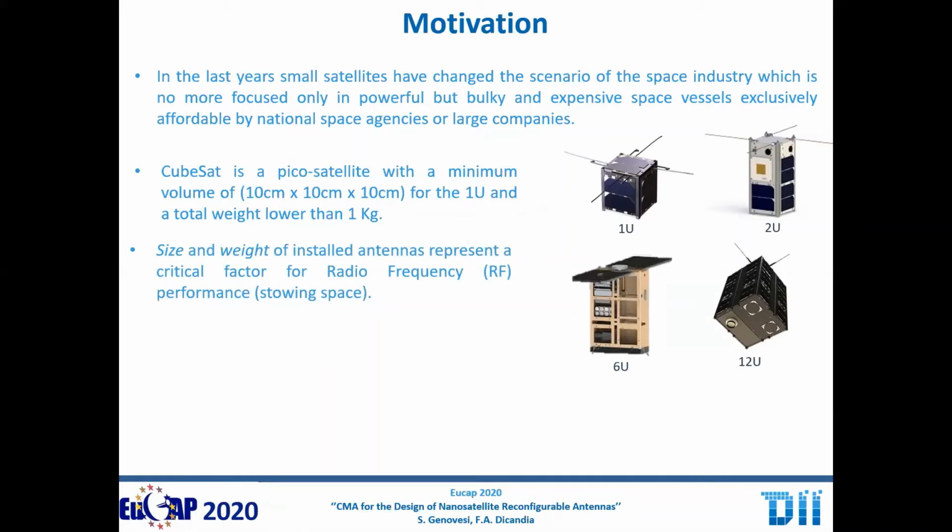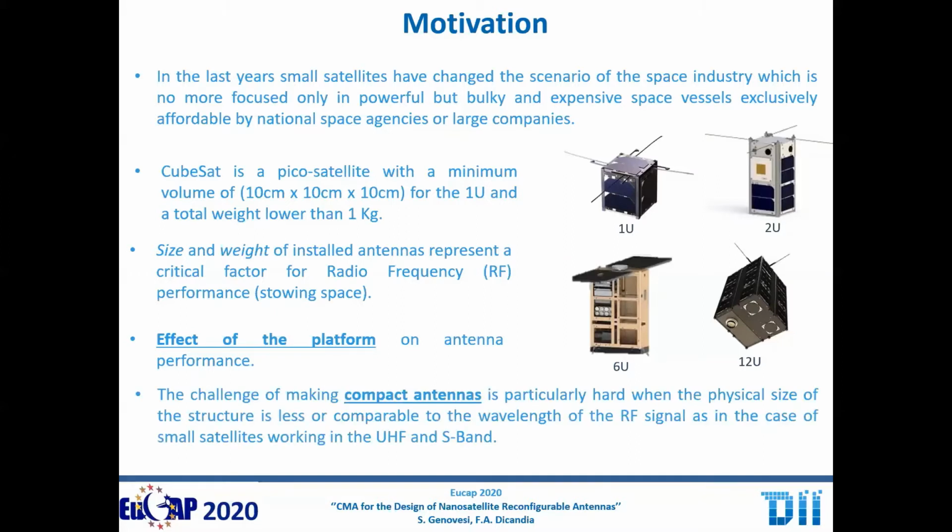Of course, since the platform is very small, size and weight of the antennas are a critical factor, and especially also the stowing space if we need to deploy antennas. And also the effect of the platform is really important, especially for, again, this kind of platform in which the physical size of the structure is comparable to the wavelength. And this is particularly true when we are considering UHF and S-band.